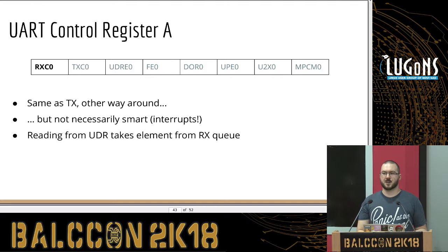Now, how does that work when combined with transmitting? If you read from the data register, you'll get different behavior than when you write to it. Meaning, if you read from the data register, it will trigger an internal read queue, give you the top of the read queue, and move the read queue one along. And if you write to it, a whole other code will be executed. So you can use it both ways. You'll just have to remember how, and you'll have to emulate it.